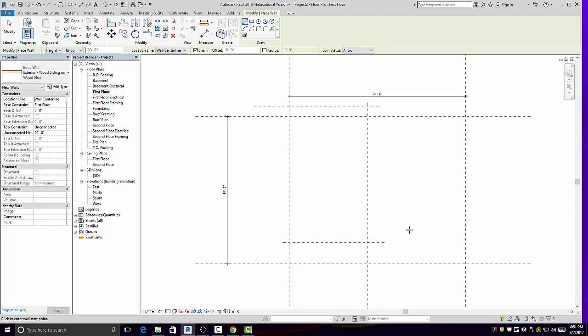If you look somewhere in the middle here, we have a description of what that wall is. That wall is fiber cement siding, 1/4-inch XPS foam furring strips, 1.5 inch XPS rigid insulation, 1/2 inch OSB.